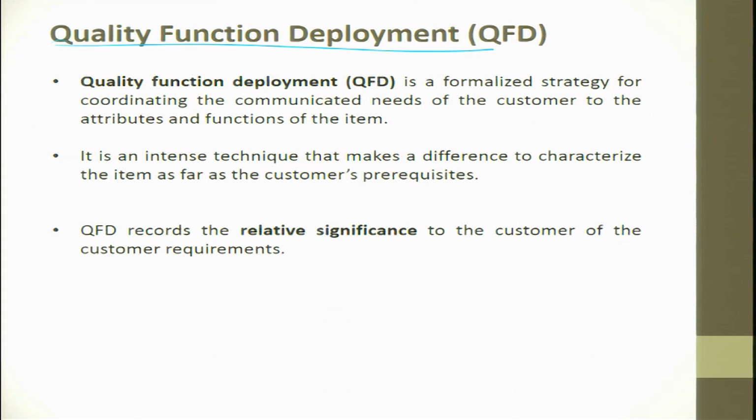So, what have you done? You have understood the voice of the customer, you have just converted this into some other indirect way and then found out an engineering specification. Then you said, okay, time within 2 minutes it should do. So, what are all the techniques available for the 2 minutes? Microwave stands outstanding, pick up that fellow and there ends the matter. Understood? Quality getting converted into engineering specification. The tool used is quality function deployment.